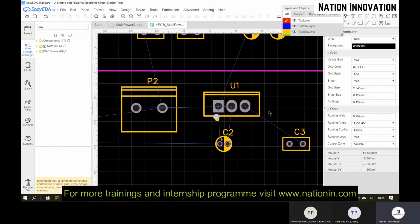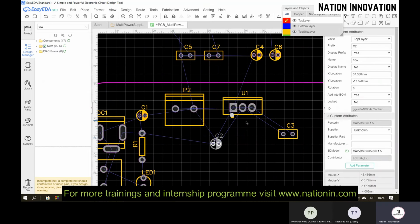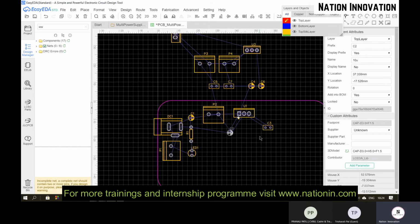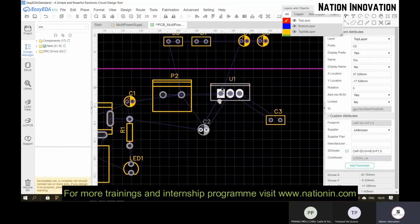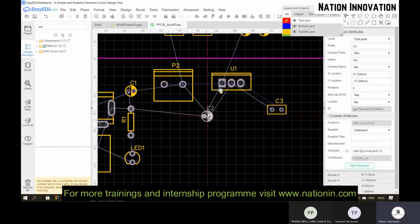Because the voltage regulator will dissipate some heat, so if it is facing at the inner PCB, all the components may get burned. So make sure that it has to face outwards. So whatever heat is dissipated, it will go outside and it will not damage our components.